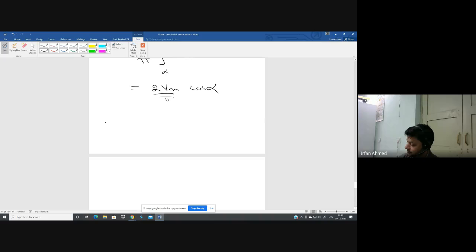And then if we substitute it in the expression for speed, omega m will be equal to 2 Vm by pi k cos alpha minus Ra by k squared into t. Okay? So that is the expression for speed. So as you can see, in the case of continuous conduction, the no load speed is a function of alpha. Okay? As you change the value of alpha, your no load speed will change. Okay? However, the slope is still same.